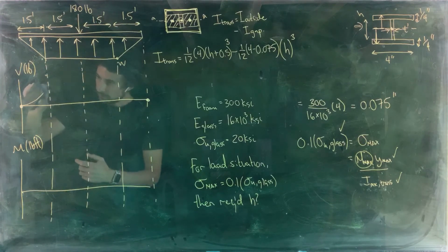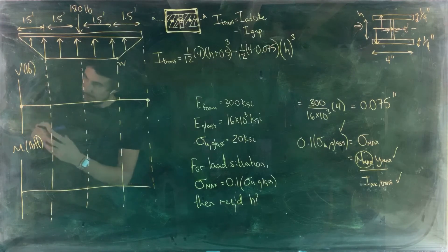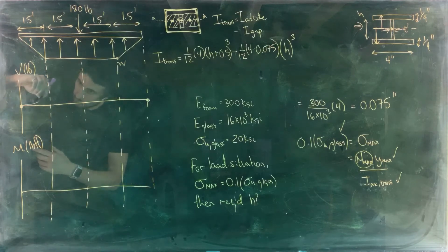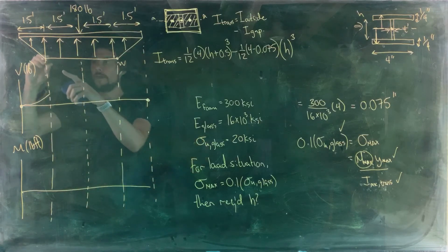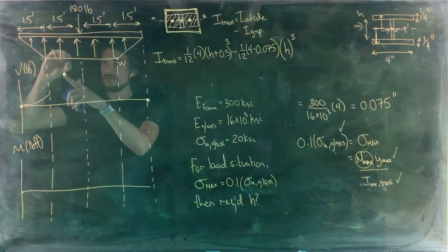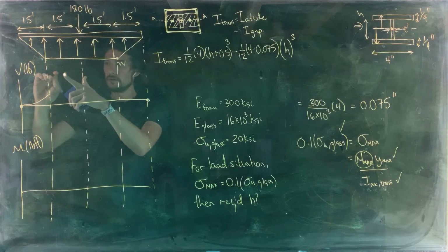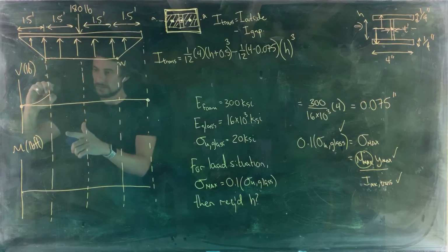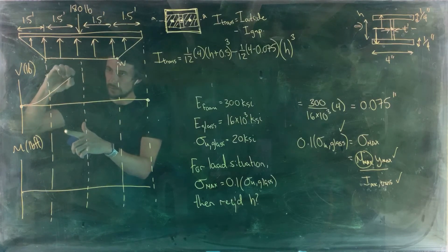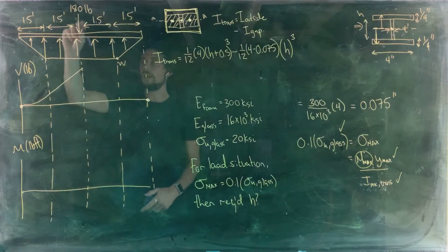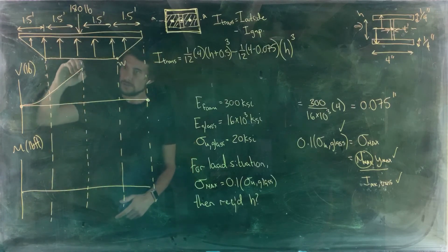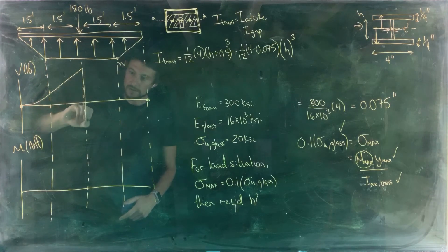Maybe I'll go a little bit less on that final slope. There we go. Okay. Then we've got constant values of distributed load. So we need to have a constant positive value, so constant positive slope. So I'm just going to continue along from the slope where I left off and draw a straight line. And then we've got a downward point load, so we're going to jump down.